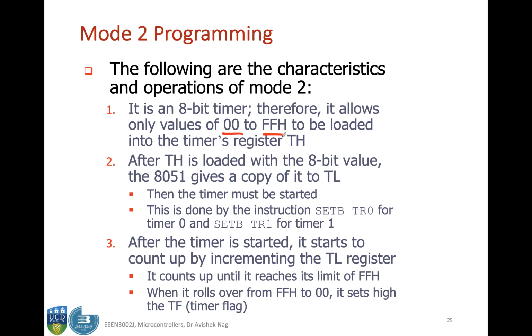The first characteristic is this. And the value that you are loaded is loaded to the TH register. So if you are working with timer 0, you load to TH0. If you are working with timer 1, you load to TH1, okay, and you load an 8-bit value to this register.